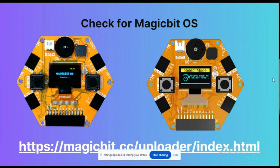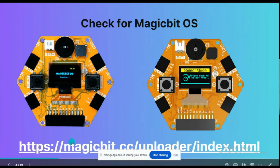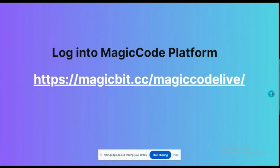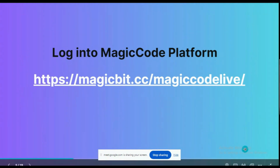If that is not there in your Magicbit, then you have to log into the Magicbit uploader, which is given through this link, or else you can search for Magicbit uploader in Google or in your web browser and upload the Magicbit OS. After uploading the Magicbit OS, you can disconnect it from the Magicbit uploader, and then you have to log into the Magic Code programming platform. You can use this link, or the link is given in the description below also.